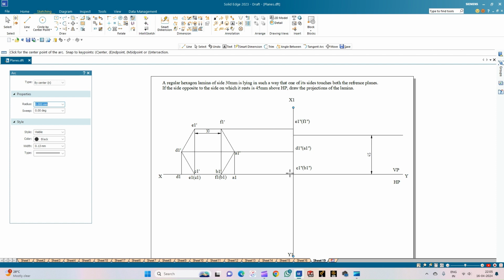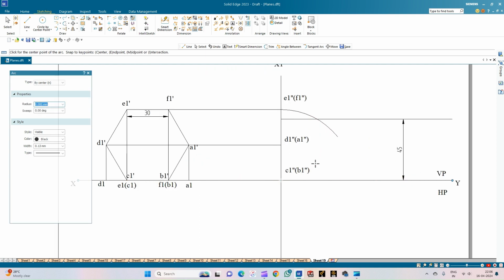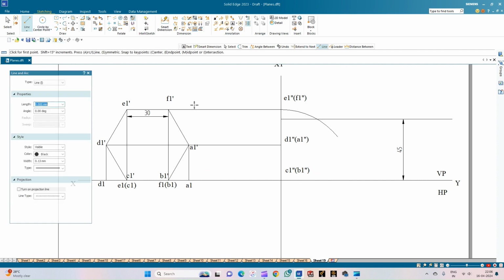So from this point of intersection I am going to measure this height and then cut an arc on this 45 line, the line which is at a distance of 45 from the origin. So now since the side view is visible, let me draw it using a thick line of thickness 0.50. So from the point of intersection, this is the side view, correct?